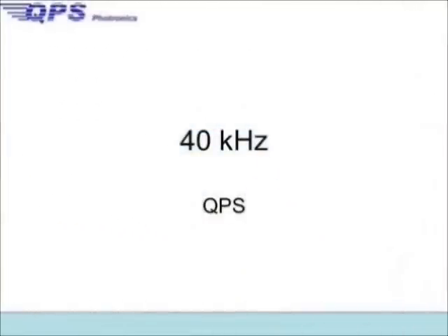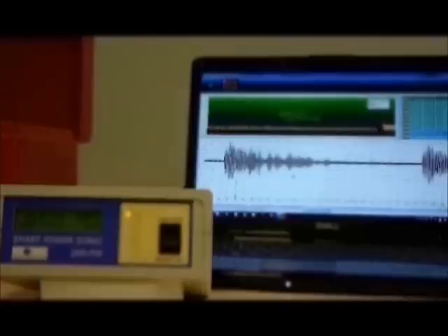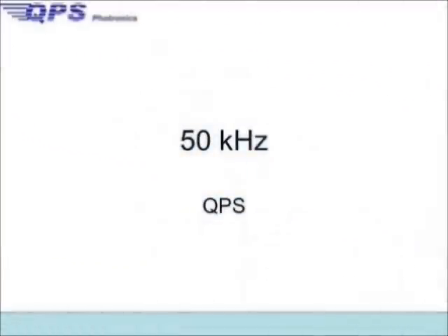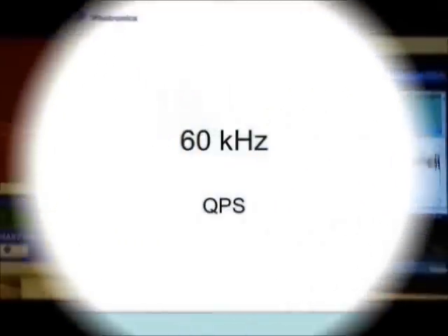Now we set the frequency at 40 kHz. The reflection still shows multiple peaks, but the attenuation is clearer. Moving to 50 kHz, the number of peaks further decreases. At 60 and 70 kHz, the amplitude has slightly diminished.